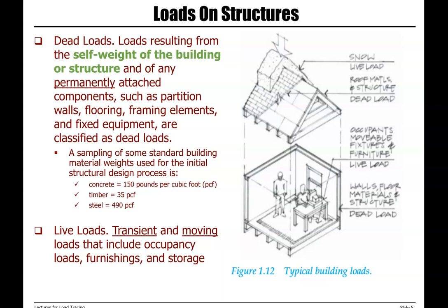Dead loads, again, dead loads are loads resulting from the self weight of the building or structure. Or basically, it's any permanently attached component, such as partition walls, flooring, framing elements, fixed equipment. Any type of load that is applied to the structure for a long period of time or a permanent load is considered a dead load.